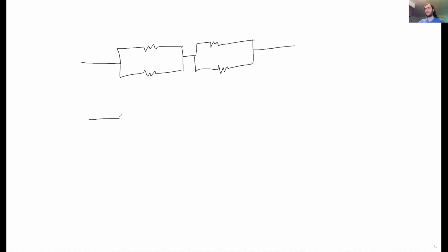Okay, so let's get back on track with this problem. What are our combinations that we have? Do we have all 10 of them? Well, I'll let Hillary talk because I've been talking a lot. For me, I feel like I only have 8 combinations. I have 10, but then I get the same equivalent resistance, so I'm unsure if those count. So this one here, 2 in parallel in series with 2 in parallel is identical to 2 in series in parallel with 2 in series. So these two are identical, but they count as 2 different combinations.